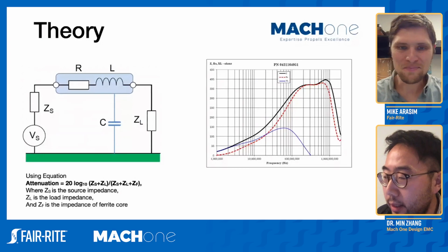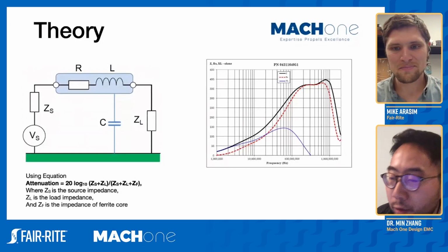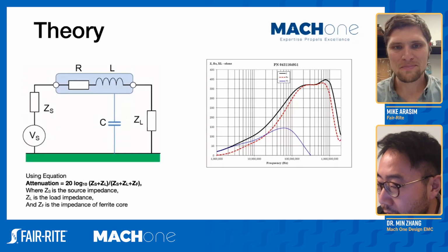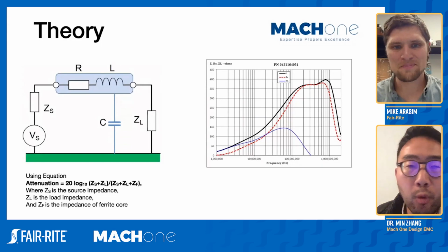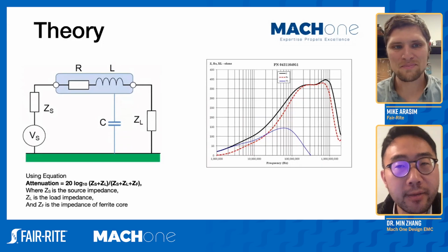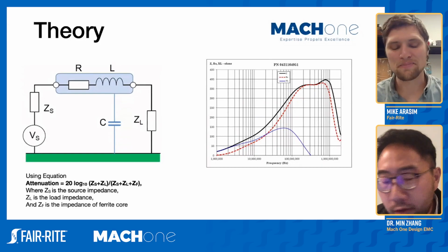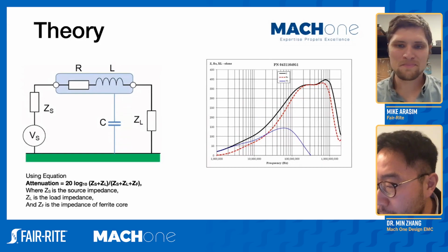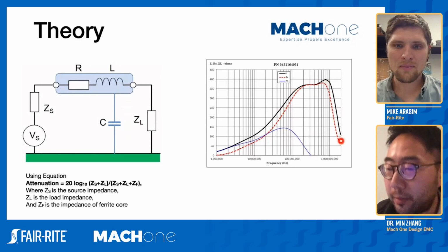I guess for me as an EMC engineer, I never really check the inductive curve because, as you said, I treat a ferrite core more like a frequency-dependent resistive part. But is there any occasion where people actually want to use this inductive characteristic curve, or most of the time do people just look at the resistive curve or impedance curve?